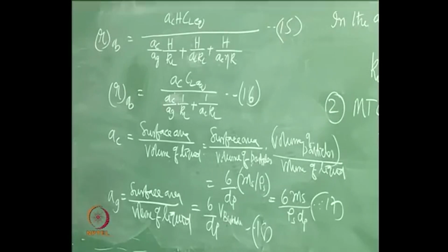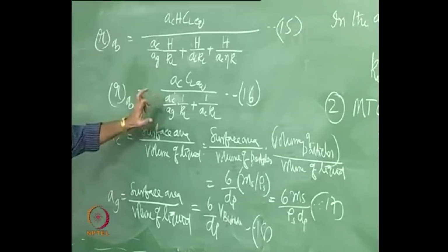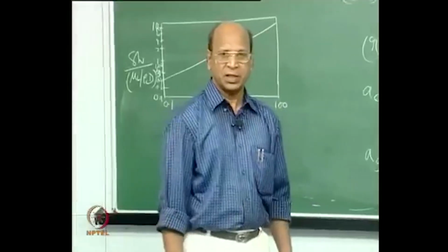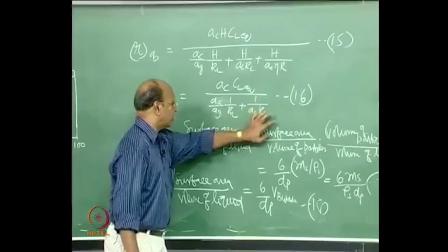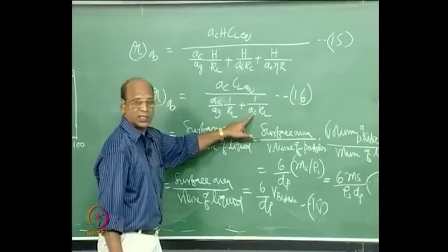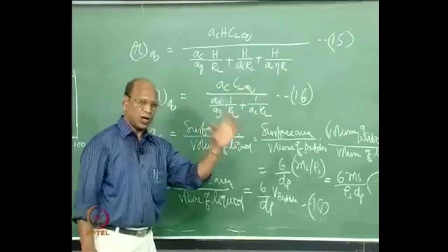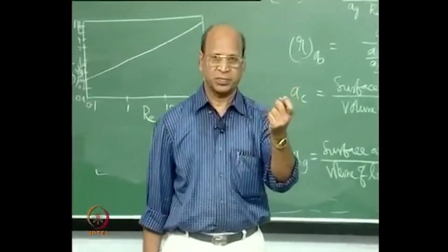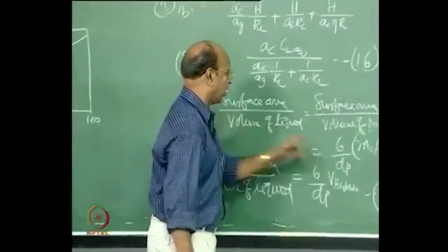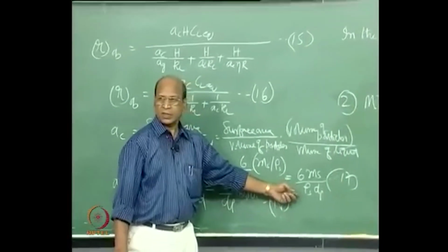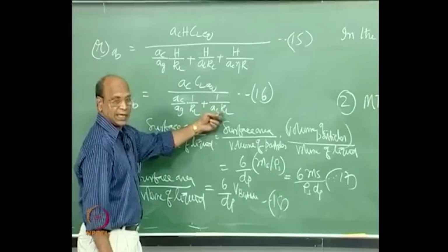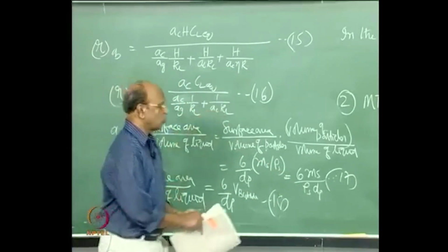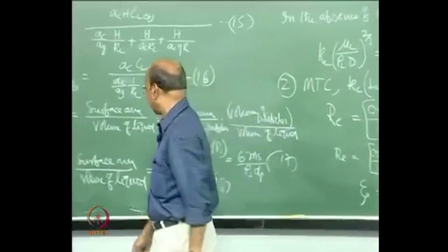If I am finding out that I have large number of small particles, catalyst particles, so that means I can neglect now this term, because AC is very large. So, 1 by AC, because large number of very fine particles. So, that means this surface area is very large. I cannot neglect this, but I can only neglect this, right. Okay, good. So, if I do that, what is the rate expression I get?